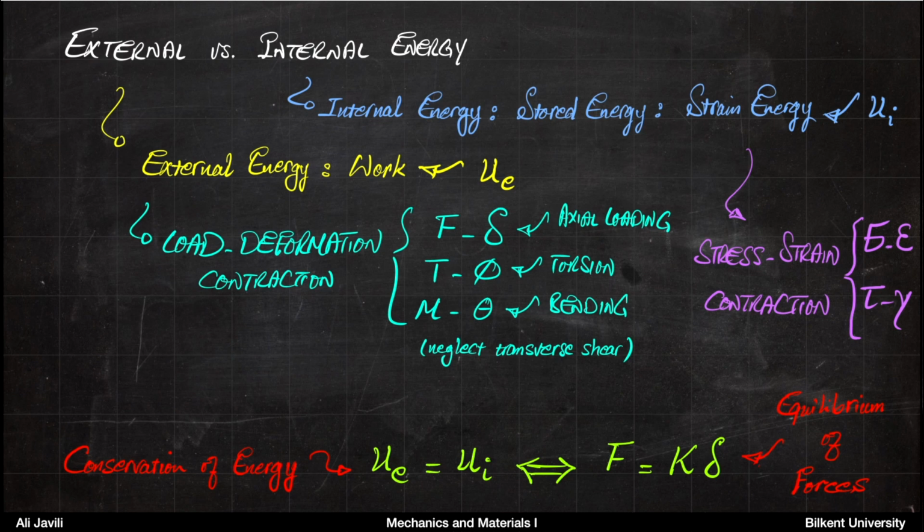So in this picture, for simplicity, we neglect transverse shear. We can argue transverse shear has less effect in this picture or is less significant, and then for simplicity, we just avoid transverse shear, but otherwise it's not really complicated either. If it's transverse shear, then your force would be shear force, and your deflection or deformation in the same direction would be the corresponding deformation measure.